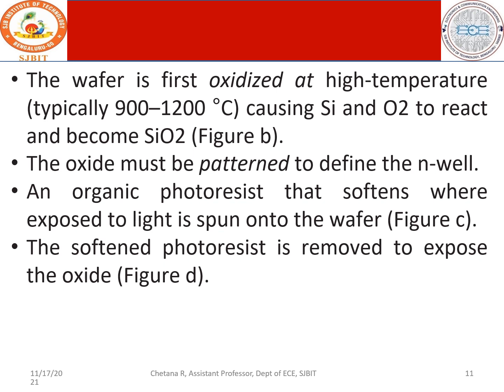So what exactly is photoresist? It is a layer which does not react with light. When light is made to fall on the substrate, the bottom layers are not affected. So photoresist means light will not have any impact on the bottom layers. And one more beauty of this photoresist is that whenever you expose it to light, it is softened. The region of the photoresist which is not exposed to light is hard. The region which is exposed to light is soft.